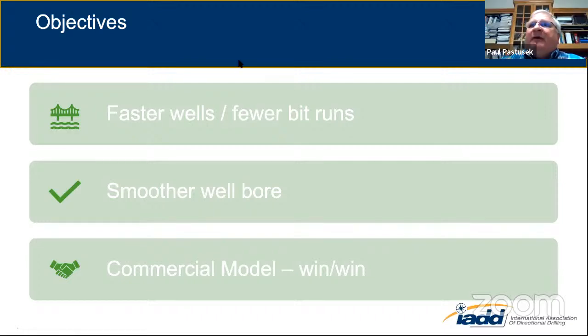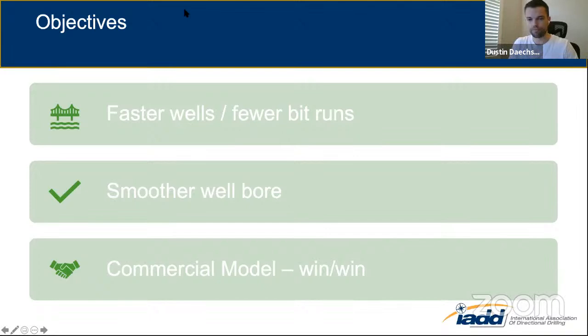For me, it's a real easy thing. I want all my drill bits to drill at rig limit ROP and drill the entire section in one run. If I have to make a trip for the drill bit or the BHA, I'm wasting time and money. I want the wellbore to have no excessive kinks, the best wellbore quality that I can get. About wellbore quality, it's not just getting the casing down. I also have to be able to get other tools down.